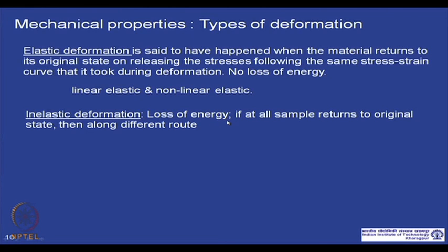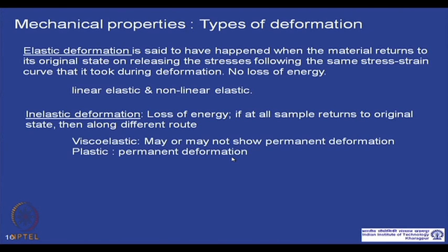So, it may deform permanently, or even if it comes back to the original state, it does not follow the same path. So, in inelastic deformation, loss of energy happens, and if at all it returns to the original state, then it does so in a different route. It could be of two different types: viscoelastic, which may or may not show permanent deformation,